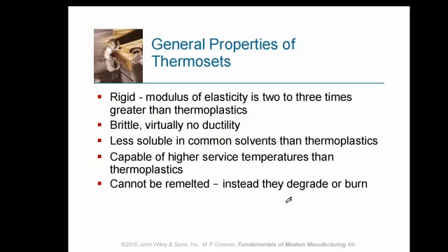They are not so soluble in common solvents when compared to thermoplastics. They can tolerate higher temperatures when compared to thermoplastics. They cannot be remelted. If you try to heat them, they burn or degrade or char.